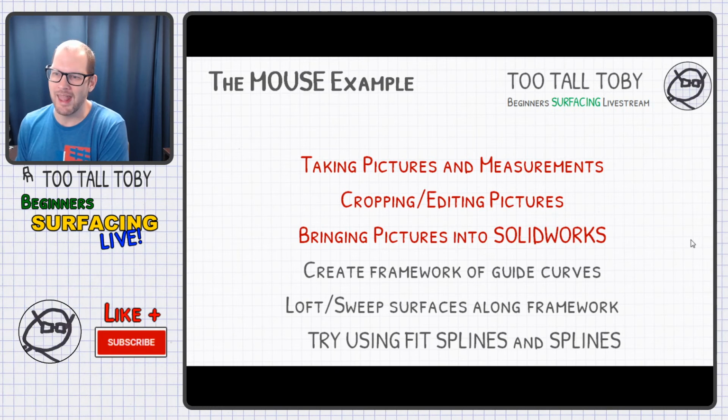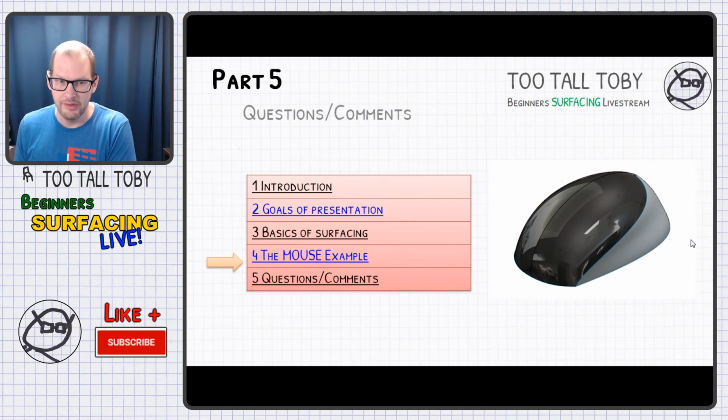But you can see here that what we do is we take our pictures, we crop and edit those pictures, we bring those pictures into SOLIDWORKS, we create a framework using guide curves, and then we loft or we sweep along those guide curves. And you want to remember that using fit spline and using projected curves and splines is going to be so helpful. And that's going to pretty much bring us to the end.